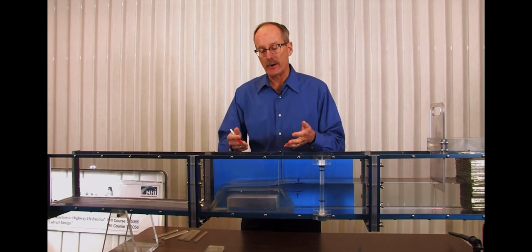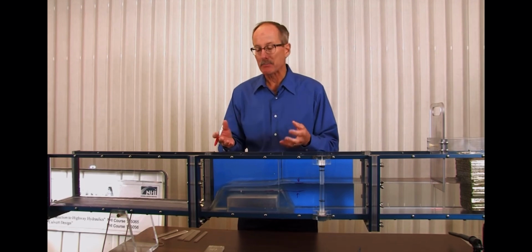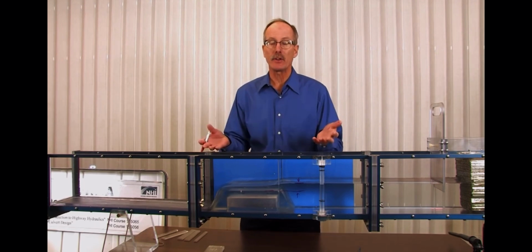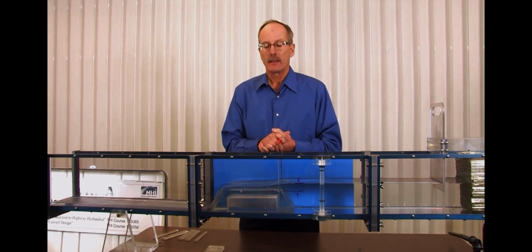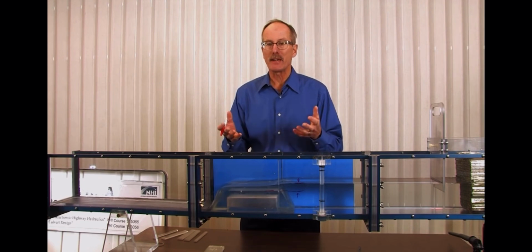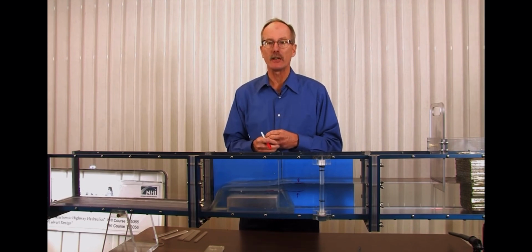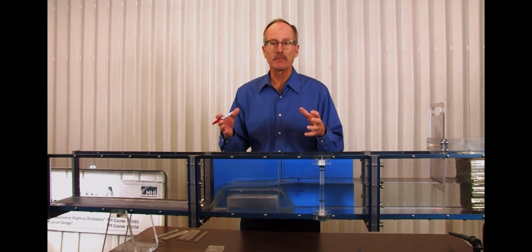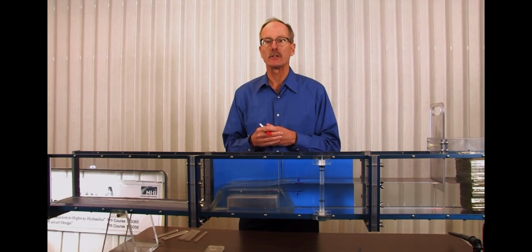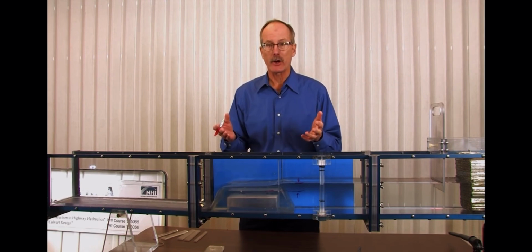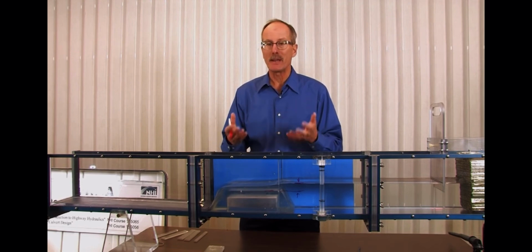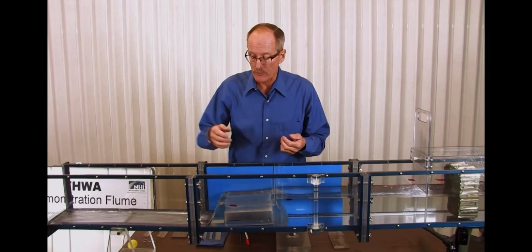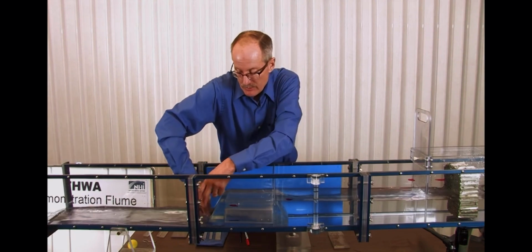So again, the broad-crested weir in the highway application gives us an opportunity to calculate the overtopping flow during a flood event, the amount of water that's going over a roadway. We also have the weir equation as part of many of the other calculations we do in highway drainage design. For example, a grate inlet in a sump acts like a weir at lower flow conditions. A curb open inlet on grade is like a side discharge weir. So this weir equation is integral to many of the drainage calculations that we do. There are other weir types, of course, and I've got a couple others I can show you.